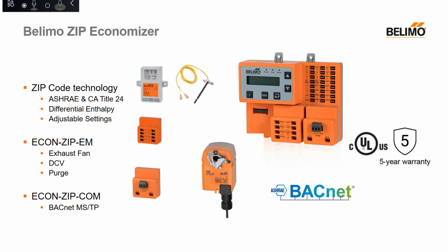The Zip is unique with its zip code technology, in which you just enter your zip code and it automatically knows what climate zone you're in, what that high limit is for that climate zone, taking away the guesswork associated with the zones and borders. The Zip Economizer also automatically knows what strategy you are using by what you plug into it.